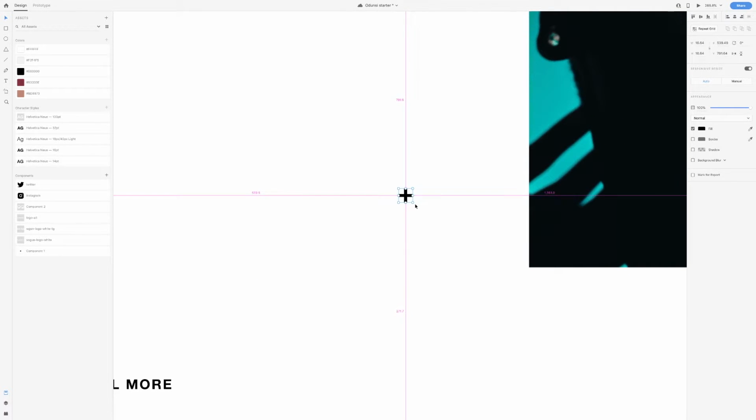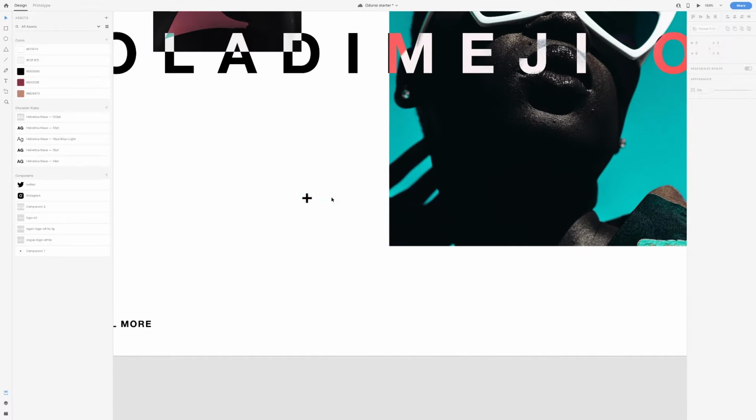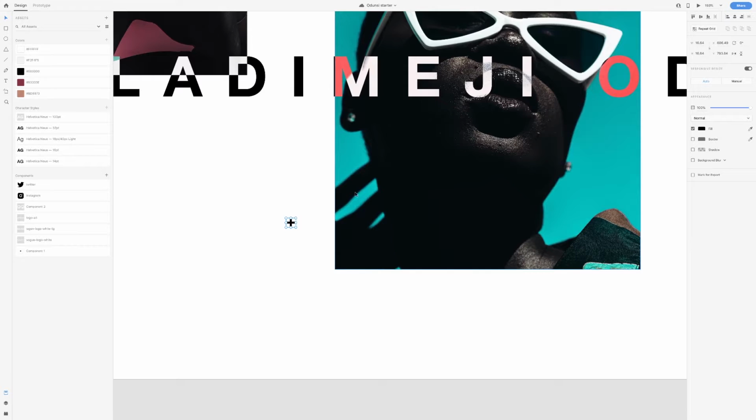And let's just blow it up a little and see if we can get it to the right spot. Since we are looking for consistency, I am going to set the width and the height of our plus sign to 18 pixels. And let's see if we can get it to where it's around 32 pixels from our image. Let's fix the X coordinates so that they are a whole number. And let's change that to 32 pixels.